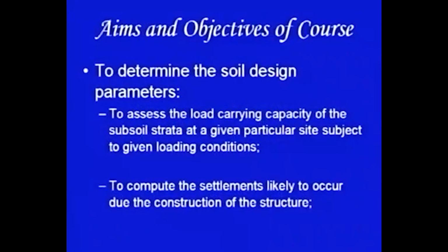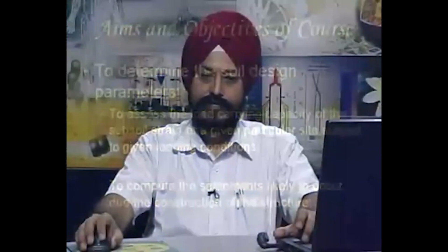Second thing which we are interested in is that we should be able to determine or compute the settlements which are likely to occur due to construction of this structure, because as I told you, it is an essential requirement that the settlements should not be more than the permissible limits. So, we should be able to find out the settlements using the soil design parameters.